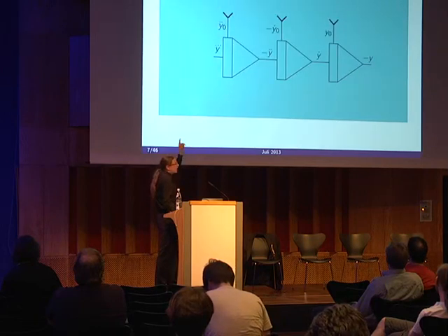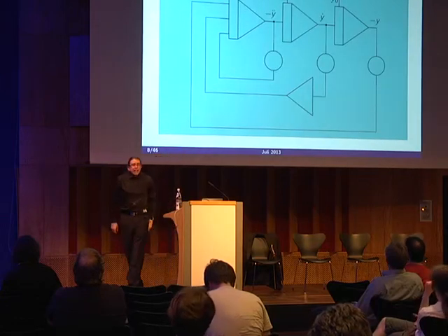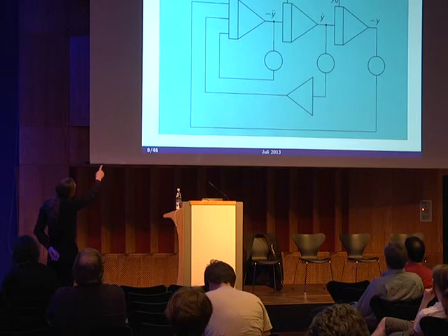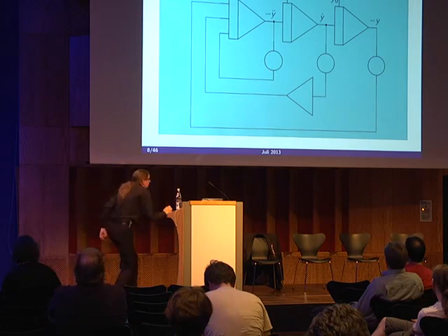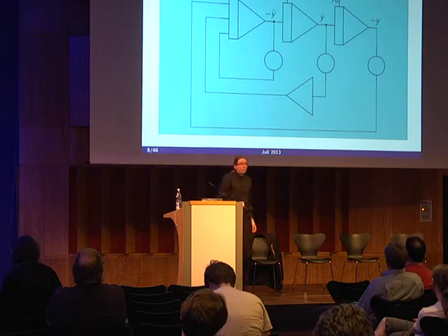So if I take this subcircuit and introduce some feedback paths, I can yield the highest derivative, which I was looking for in the first place, by adding minus y dot dot and minus y dot and minus y to yield eventually the y dot dot dot that I was looking for. And what is this? This is a program. That's a program for an analog computer.